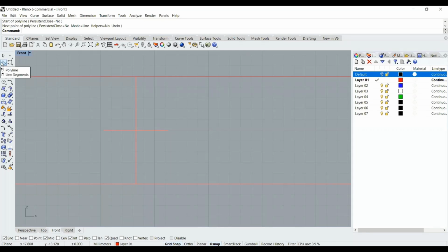So now I'm going to draw another line vertically, and this is going to help me to structure the height of this shape. So I'm just clicking here on a midpoint, and the next point on the polyline will be 4. So I want this to be 4 millimeters long, and I'm just holding shift and pressing enter. So you can't see, but actually the line is here.